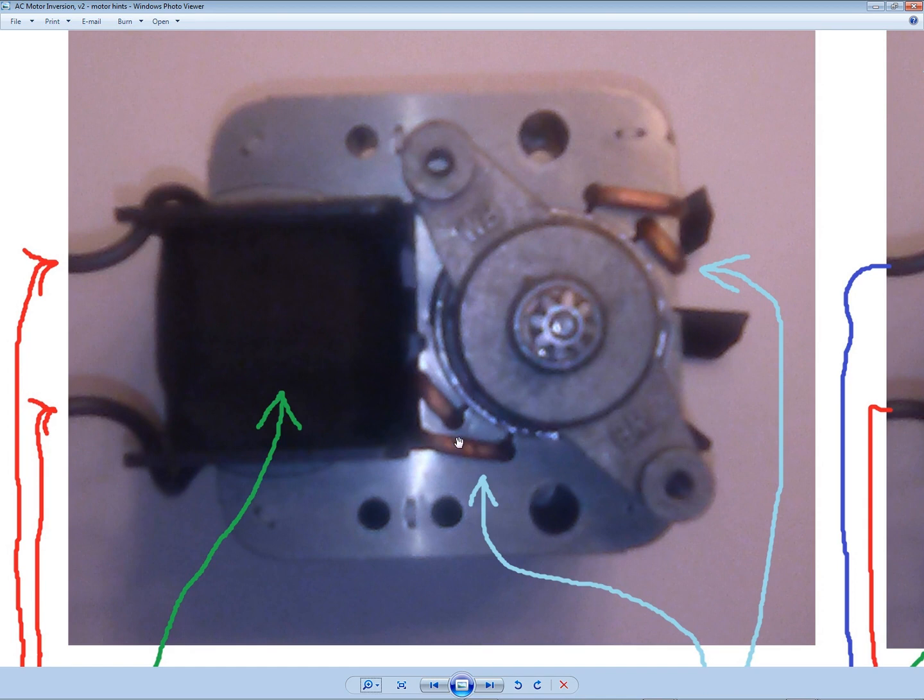Well, these are the starter coils. What happens, the AC comes in here, that's what these red arrows mean. The AC current comes through here, 120 volts, 60 cycles, and all it does is get the squirrel cage to wiggle back and forth, to jiggle, first clockwise and then counterclockwise, and it jiggles every half cycle of a 60 cycle. So 120 times a second, it changes direction. If it were not for these pair of, they are called starter coils, that's all that would happen.